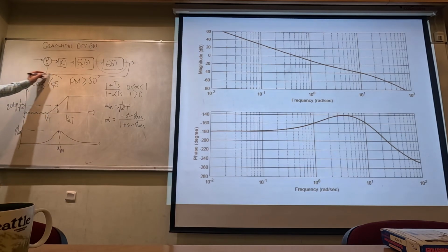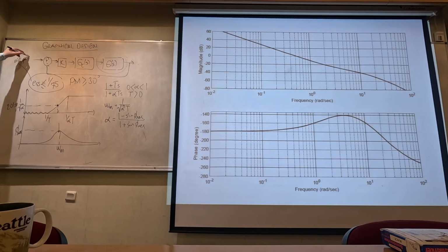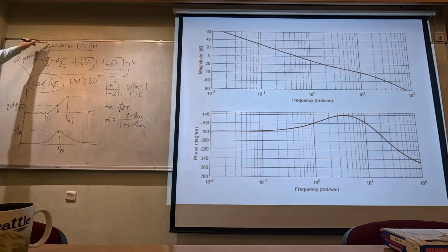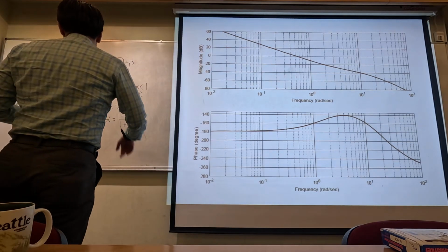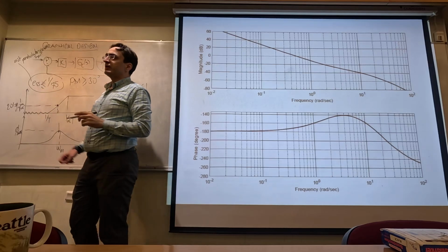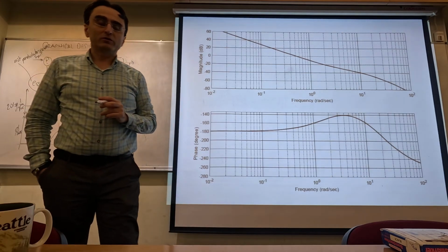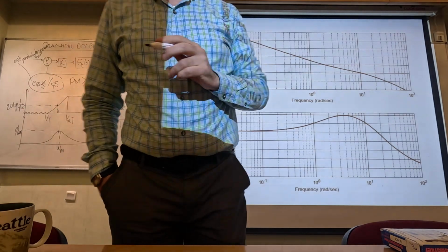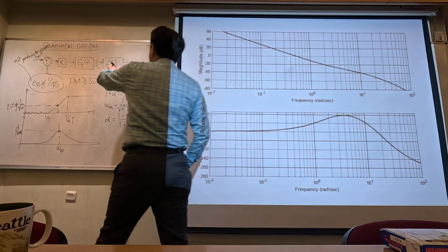So here, this is the steady state error for unit parabola input, or unit acceleration input. If I want the steady state error smaller than or equal to 1 over 75, what should be my Ka value?